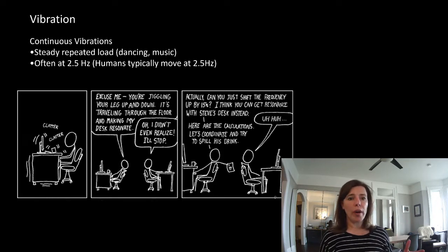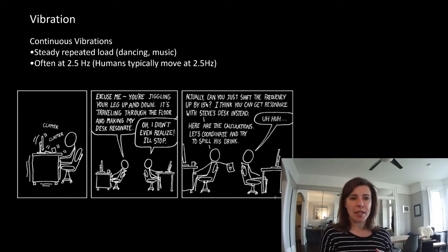So we need to worry about that vibration. And we have equations that we look at. Most of the time it's not a concern. Times that it might be a concern are lightweight structures, which sounds kind of weird, but that's because they don't have the mass to kind of resist the load, or they're very sensitive to vibration.